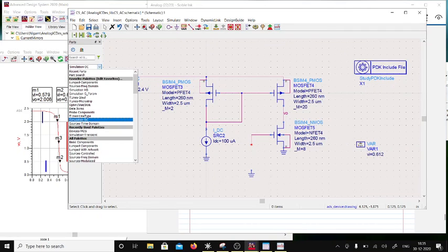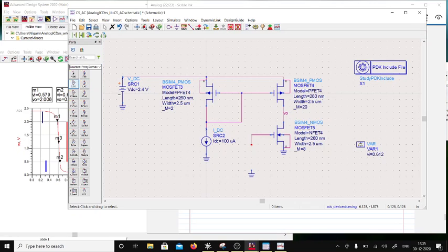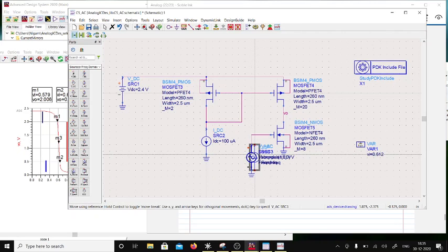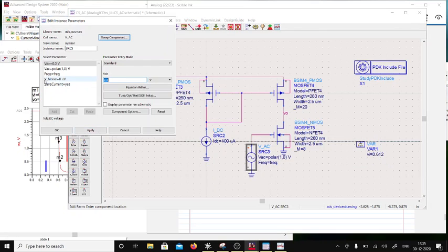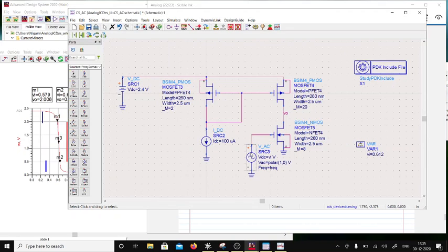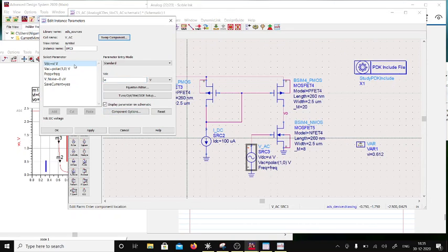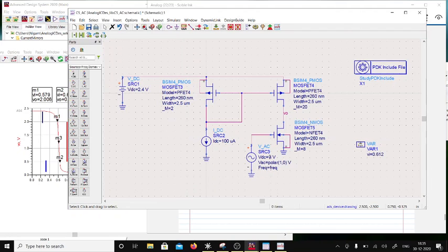And then I will put here AC source frequency domain VAC. That VAC I'll put here. Okay, and then in this VAC I'm going to have a 1 volt input, so the output would be the gain, and frequency is going to be swept, but then I am going to add VDC to be VI or V bias, right? And I will display that at the output. So I can put a voltage here also, doesn't matter. Okay, so let me just display this one, VDC, display to the output. Yeah, so this is over here, VDC.